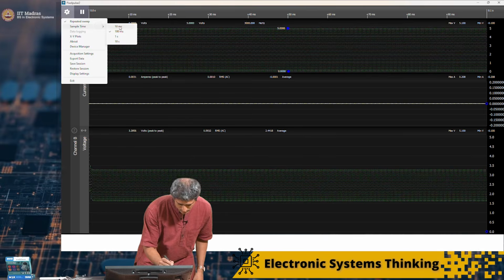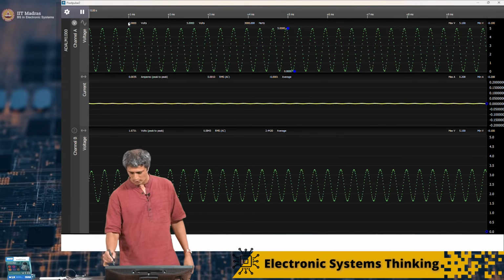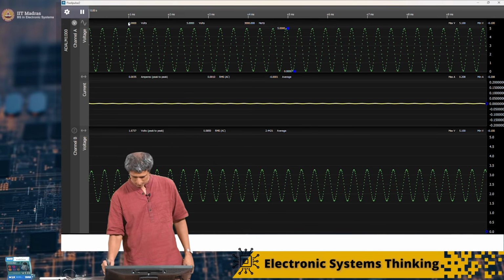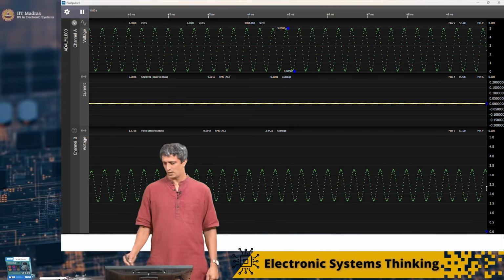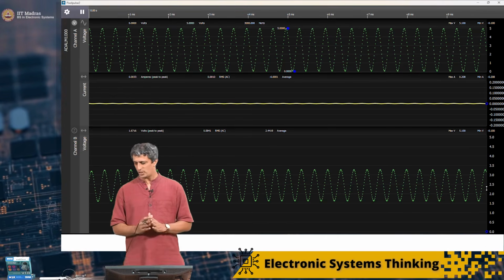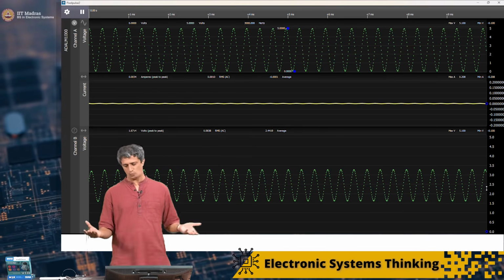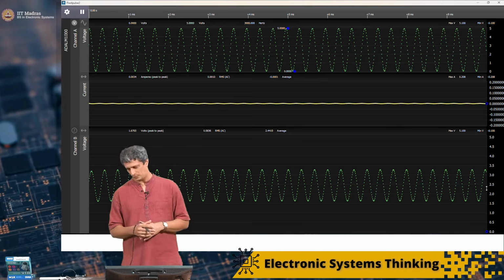You can change the sampling time again, and you will see that the input is going from 0 to 5 volt, but the output is hardly between 1.5 and 3 volts, right. So that is essentially your low pass filter output that we had shown you in the course as well, right. Okay. So with that we have finished the instructions for the first introductory lab. See you later.